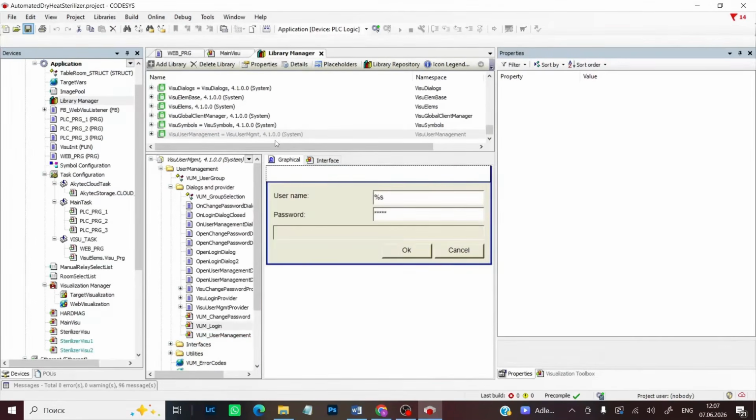But here's the problem. In this version of the library, the functionality of these dialog windows is broken, and it's impossible to roll back to an older or newer version of the library because it's tightly bound to the version of the CODESYS IDE. One way to work around this bug is to enable the Support Client Animations and Overlay of Native Elements option. However, this solution doesn't work for devices whose chips don't support overlay technology, and it doesn't always work even for devices that do support it.